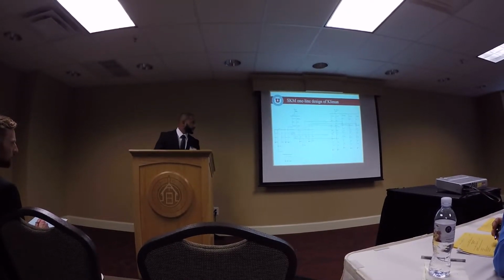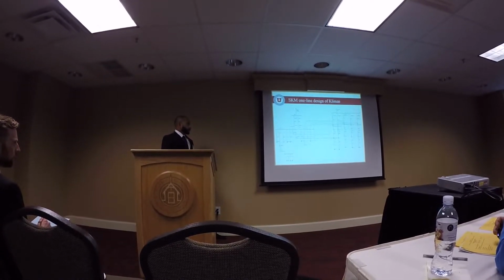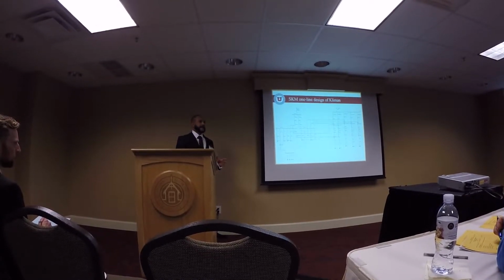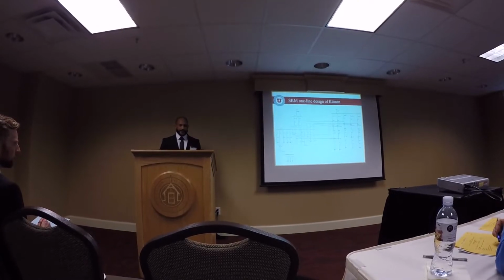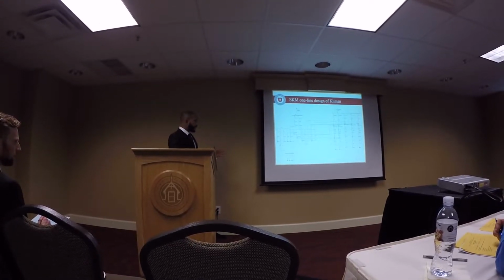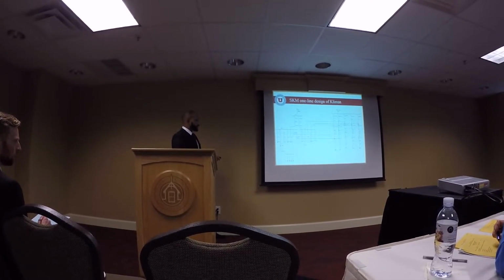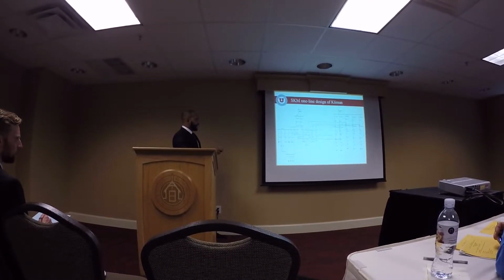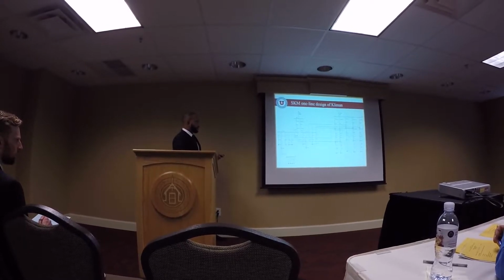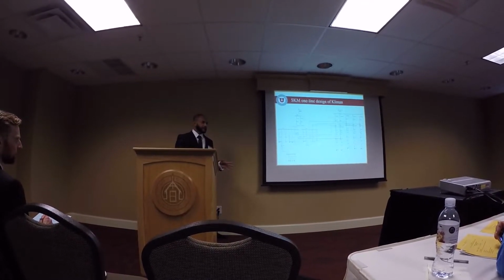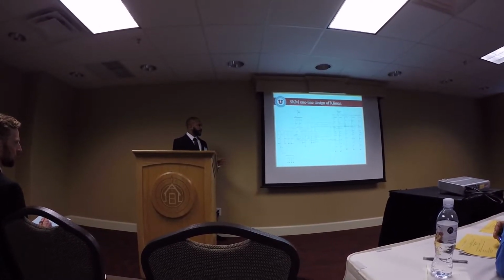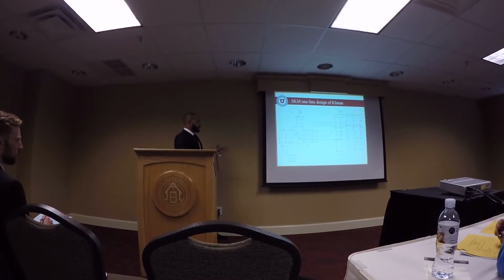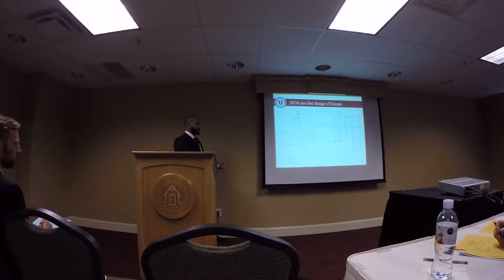This is my one-line diagram. When I was doing the one-line diagram, I wanted it to look exactly like the AutoCAD. So if a problem happens somewhere and an engineer needs to replace this main breaker, he can replace it, test it in SKM, and then immediately redline it in AutoCAD rather than trying to find it in AutoCAD. Making it look identical will make the engineer's job a lot easier down the road.